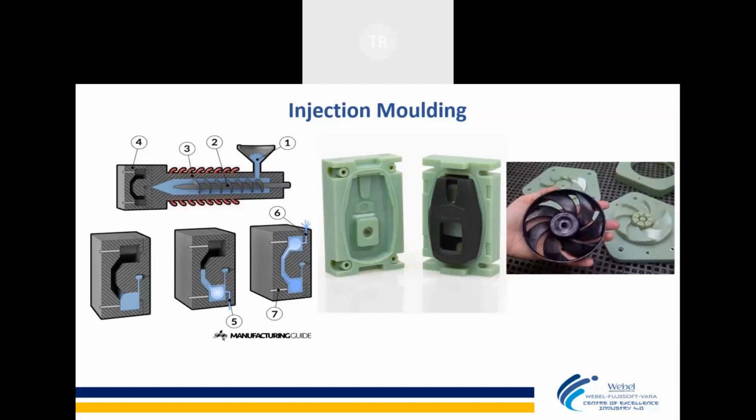Sir, actually, it's like a wax pattern we make, and from that wax pattern we give molten material inside it, and the wax diffuses and the material is made. No, that's not injection molding. You are talking about something like investment casting, where there is a wax pattern. Whenever the term pattern comes up, it's casting. In molding, we don't use patterns. Okay, I will tell.